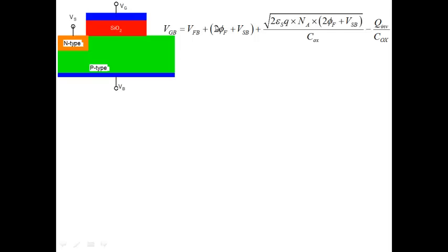So inversion charge is there, but compared to these terms it is negligible. Because remember, what is the depletion charge due to? Depletion charge comes from background doping. What is the doping order? Na. And if we say that the electron density at the surface is less than Na, electron density everywhere will be much smaller than Na. And therefore, this inversion charge compared to this term is negligible. So in my expression, I'm not saying inversion charge is 0. I'm neglecting inversion charge with respect to this. Okay.